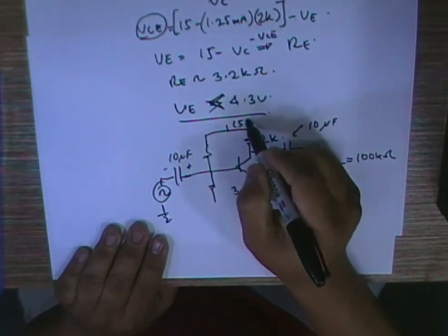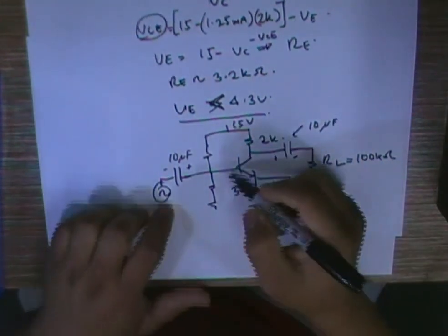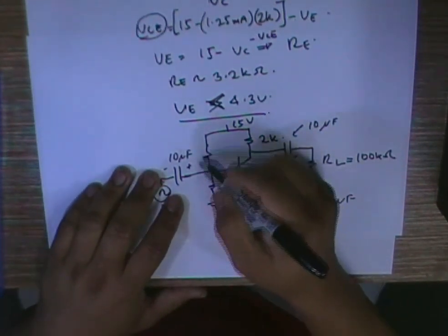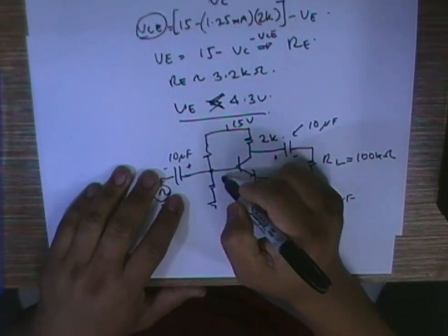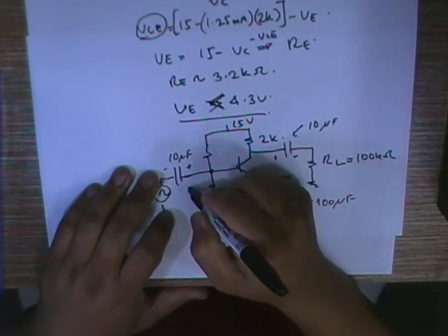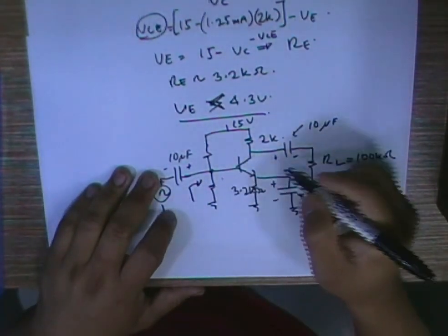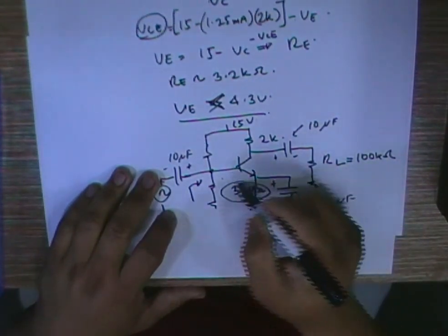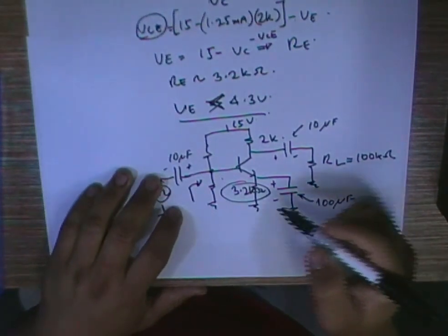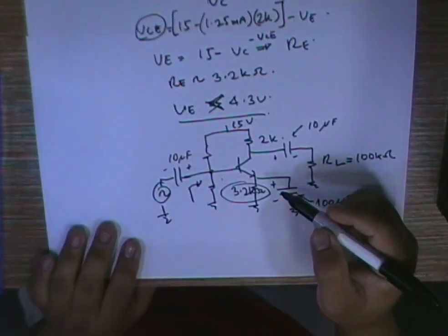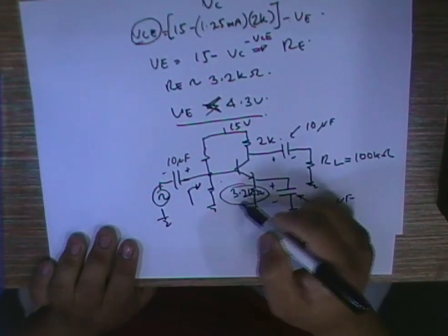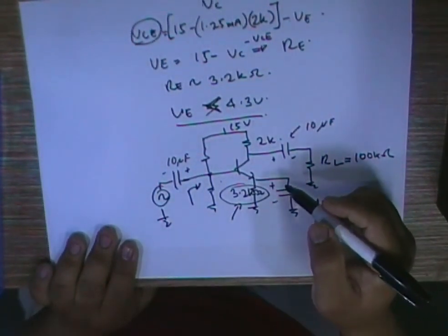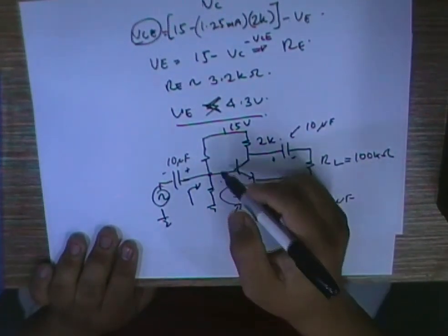Say this is 15 volt. If you adjust this thing, you can see that this will only change the input impedance. It won't change that much the characteristic of the amplifier because the gain is basically set by this. So if you do the simulation for this, you can see that by changing this thing, I can change the gain of the amplifier.